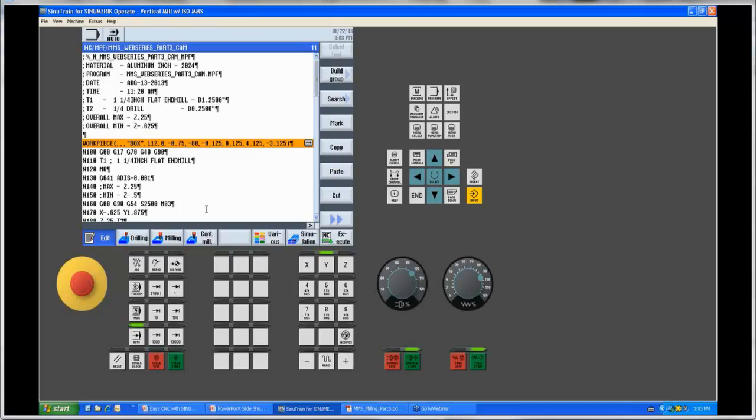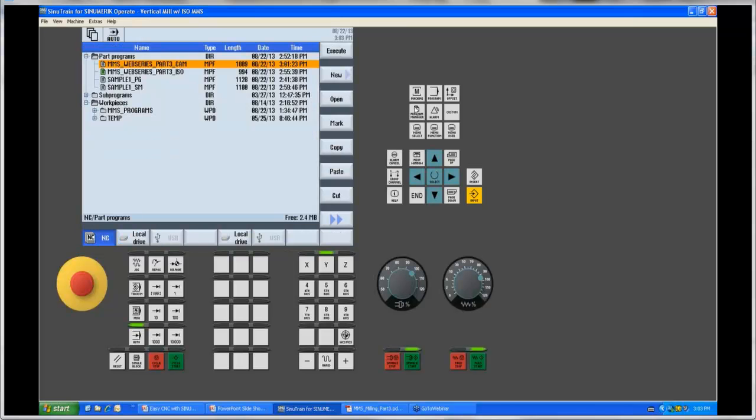Okay. Thanks, Chris. Looks like we have time for just one more question before we conclude here, and that is, can you use the ISO mode for 5-axis programming? Like I kind of said earlier, you want to be careful with ISO once you get to any of the higher end technology, specifically when you get to 5-axis. There is limited functionality we support within FANUC's protocol. We do like their rotary workpiece compensation and whatnot. But when you get to true 5-axis simultaneous cutter path, then I would certainly recommend you stay to our protocol of G code using our commands. So it's limited. Be careful with it.